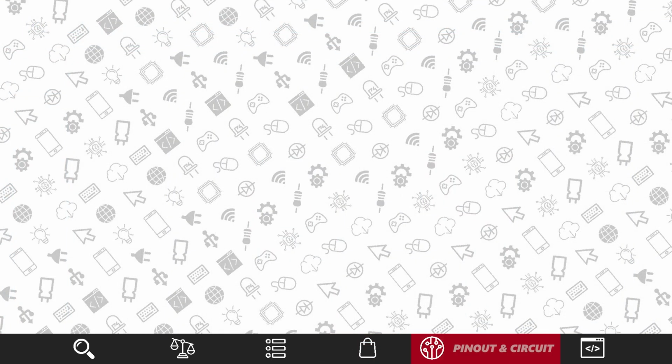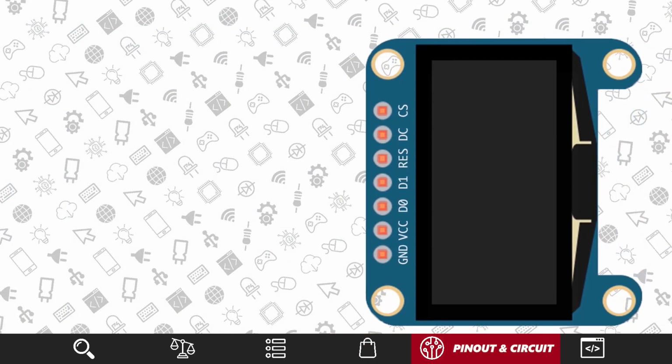Take a look at a map for the interface of OLED and Arduino. As we said before, our module supports the SPI connection, but the problem is that in different modules, different names are chosen for the pins. For example, the clock pin is also written as D0, SCK, or CLK in some modules. We try to use all the different names here.